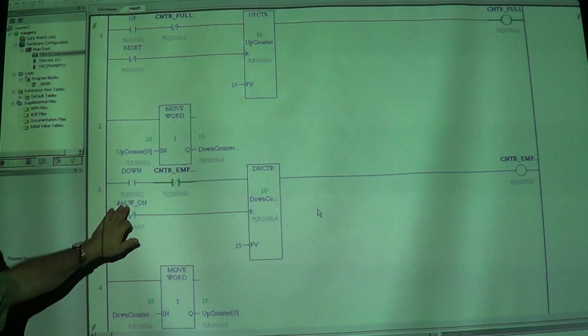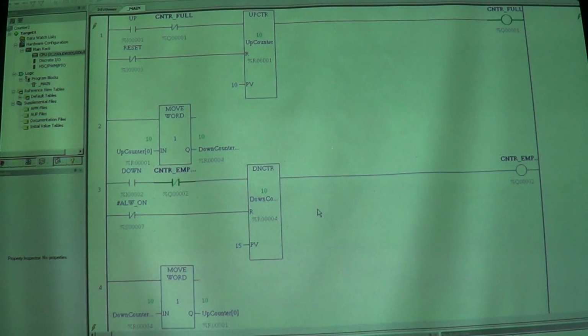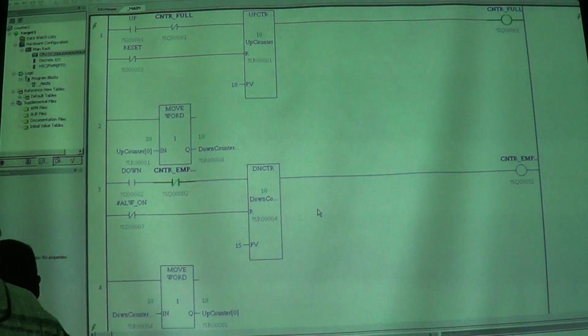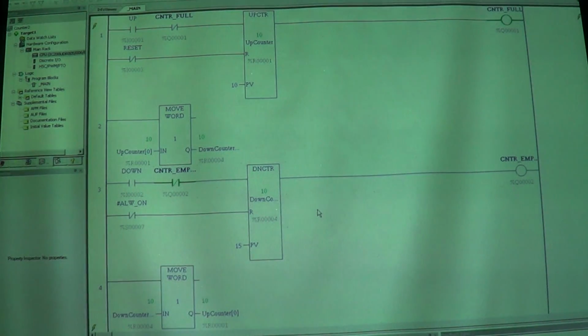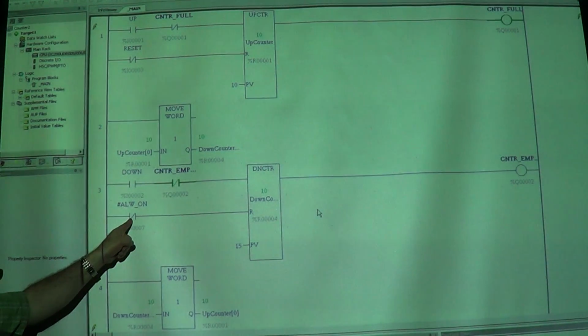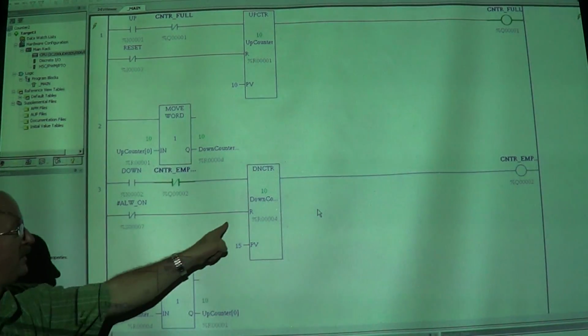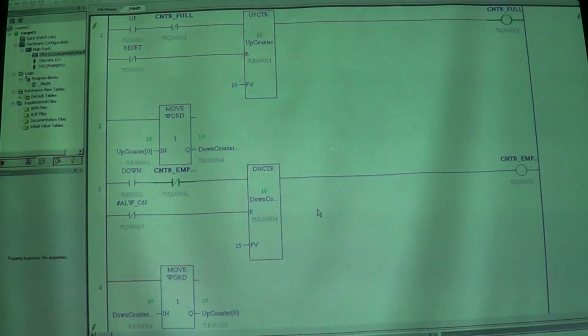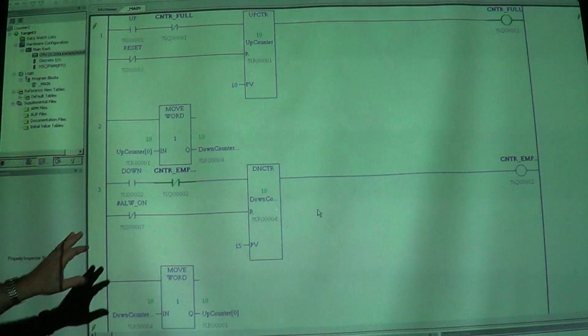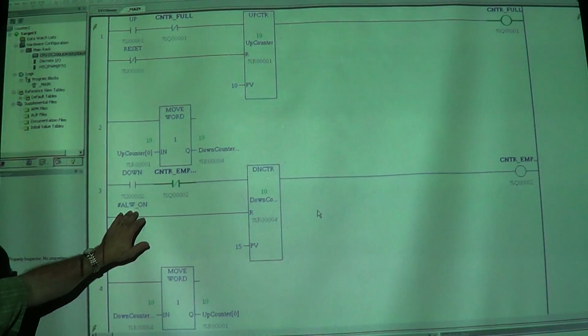I have the system input on a coil that's called always on. If you have a coil that's always on, that means this will never reset, will it? The coil is always on. That will always be open. This will always be false. There's no reset.